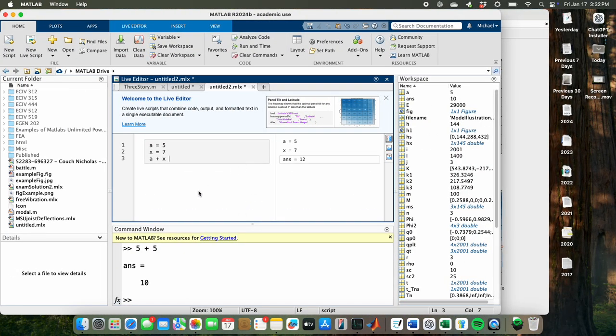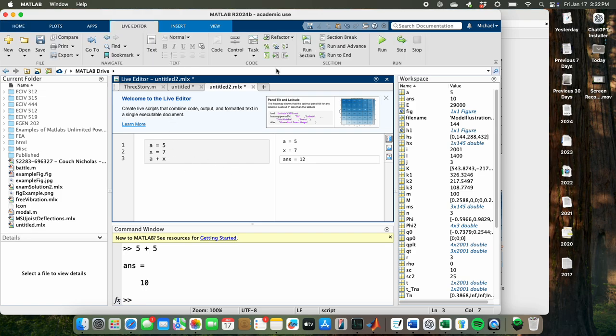And so sometimes if you're not in the current directory, if it hasn't been saved, so if I'm in this editor and I go to run it, you'll get better at this, but I make this code and I have to tell it to run. It doesn't automatically run unless I tell it to run. There's this little command up here under editor that says run. And if I hit run, it'll evaluate it. It'll actually go through and carry out that code. Sometimes it'll kick it back at you because if the file you're working on isn't in the current directory, it'll say, hey, this file's not in the current directory, I can't do anything about it. And then it'll give you a prompt that says, do you want to change directories?